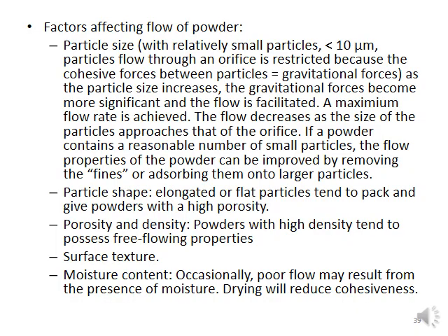Factors affecting flowability include particle size, particle shape, porosity and density, surface texture, which is being rough or smooth, for example, and moisture content. Small particles usually have problems with flowability. Particles smaller than 10 micrometers mainly have this problem.